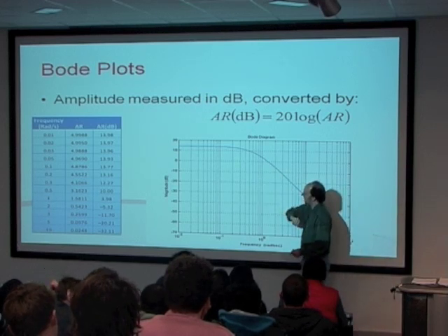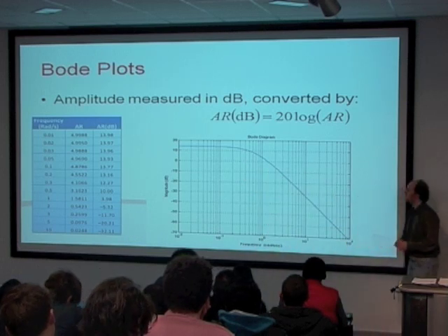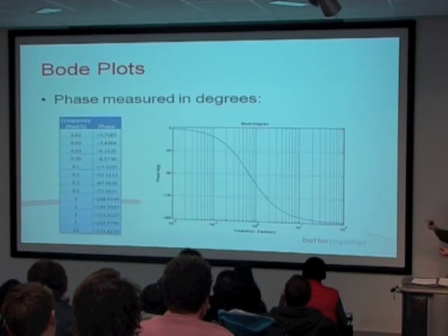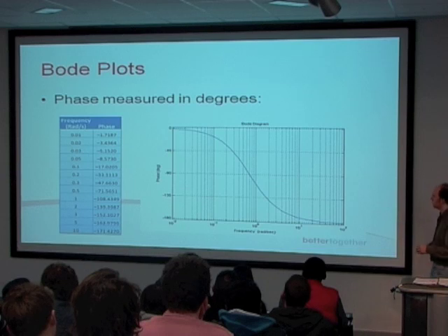You pick off that range of frequencies and you just plot them, and you draw a line connecting everything together. And the same with the phase diagram. You just take the same type of paper, you plot the phase like that as well. And you want to choose a range of frequencies that will suit your data.